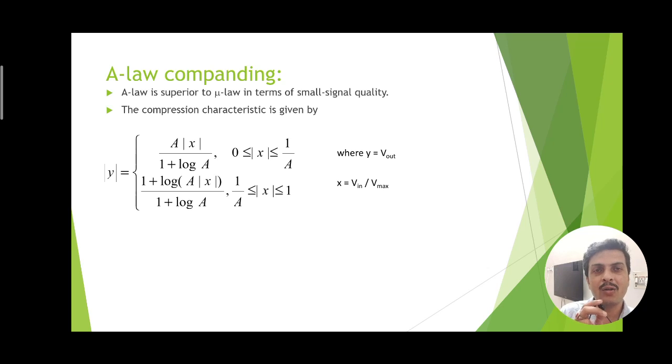Similarly, A law has some other mathematical expression, but the target is the same. That is, we need to reduce the quantization error so that the error of recovery of the signal at the demodulator will be less.